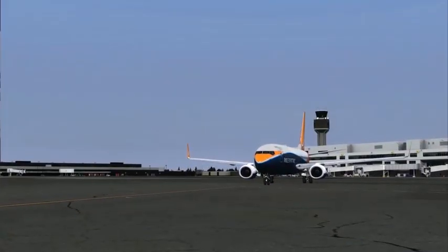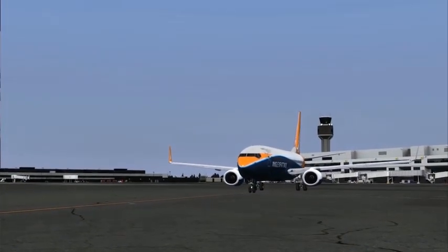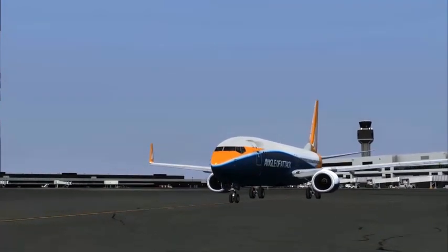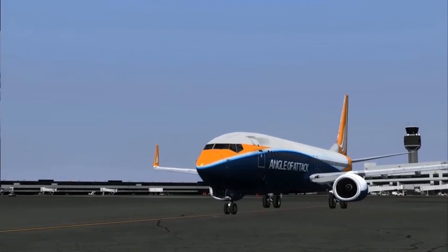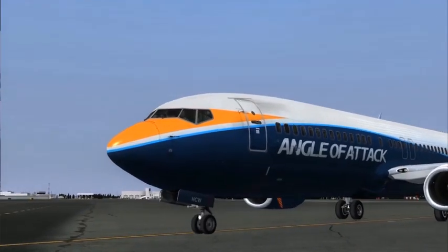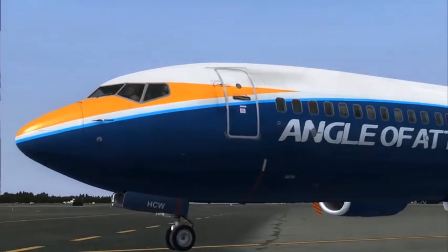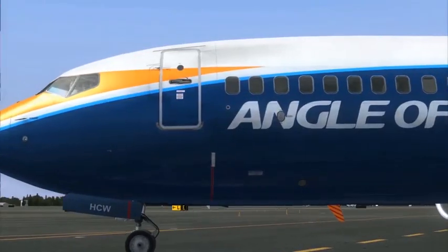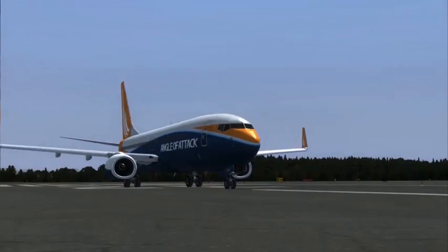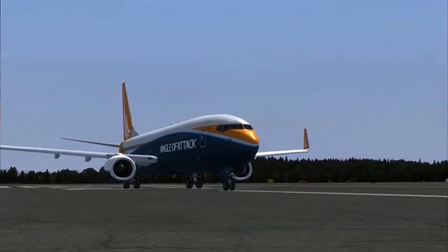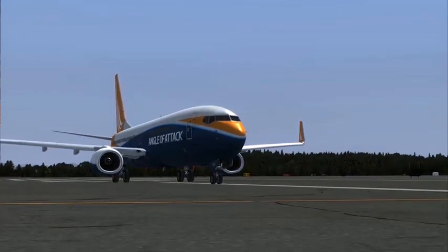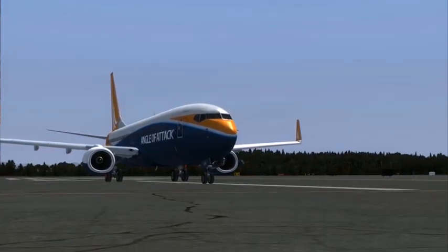On ground, the airplane is unpressurized and the outflow valve is fully open. The system senses the ground condition when the air-ground system senses compression in both main landing gears, engine N1 is lesser than 50% for 1.5 seconds or more, engine N2 is lesser than 84% for 1.5 seconds or more, or when both engines have been shut down.